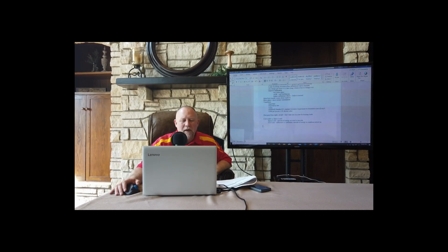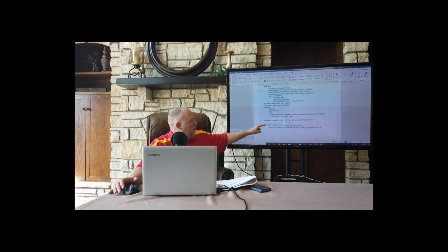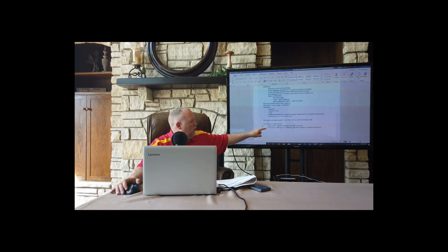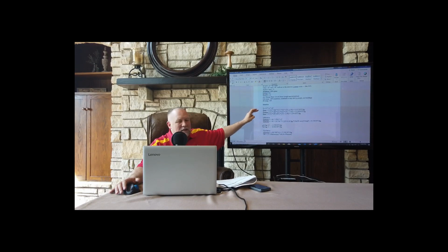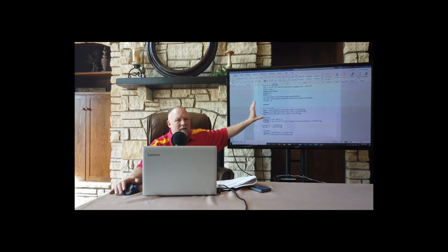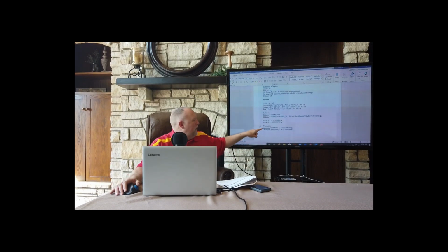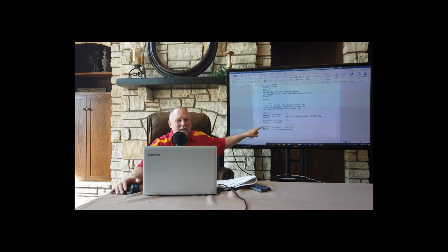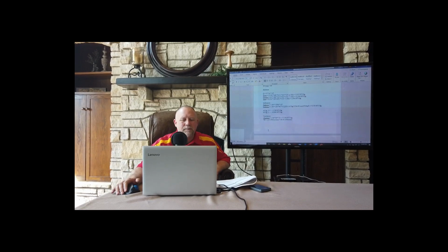All right, a couple of other important terms here. Notice space loads versus coil loads. Space loads are all these things: heat transfer from walls, windows, roof, infiltration. Those are all space loads. They directly affect the temperature in the space. A coil load is all of that stuff plus the heat loss from the ventilation that we bring in on purpose up at the air handler. And that gives us our total coil load. In other words, the maximum amount of energy that we've got to add to a building to offset all of the heat loss.